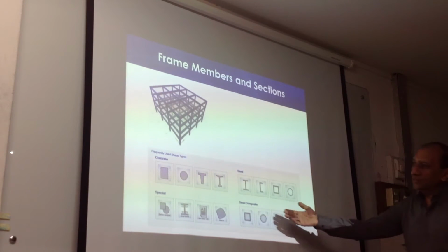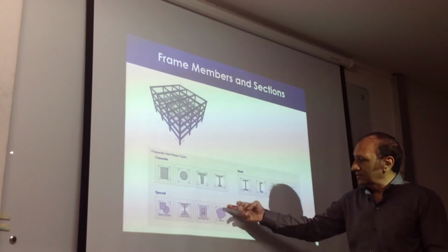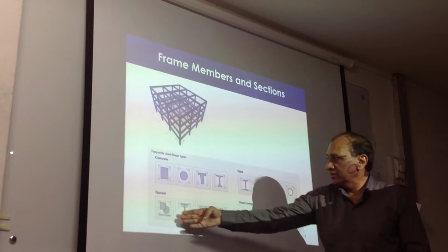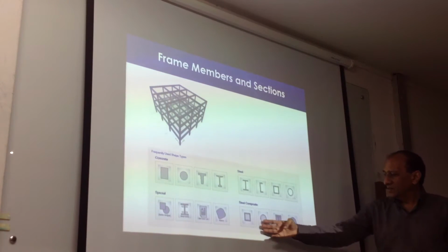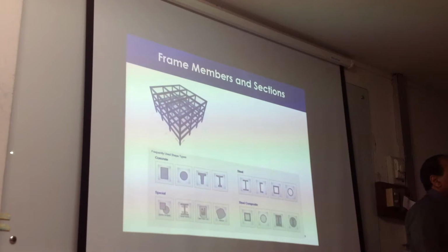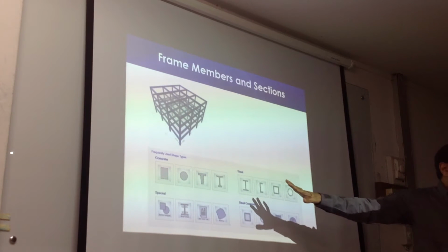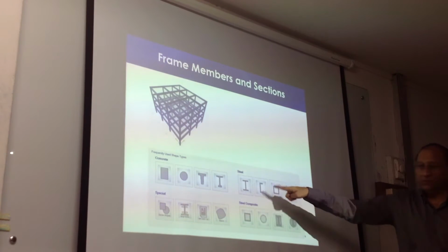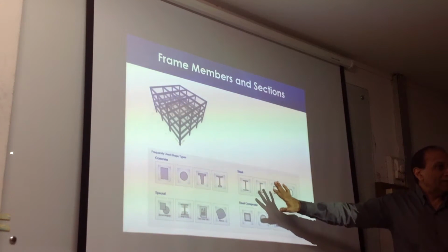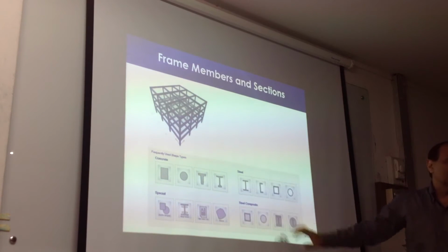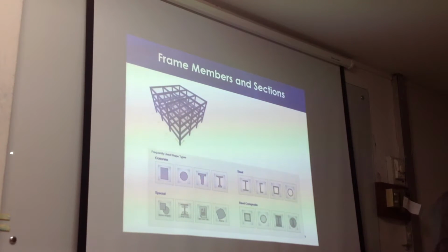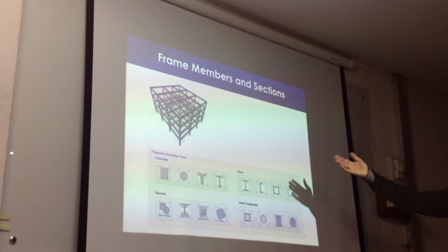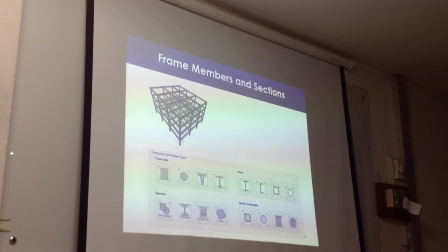And they may have any cross section here: rectangular, circular, this one, general section, built-up section, composite section, steel section. All those kinds of sections may be there. Steel inside concrete, concrete inside steel, concrete inside steel inside concrete, and all these combinations, right? Plus pre-stressing, post-tensioning as forces on top of that. And reinforcement anywhere. So we have a complex problem in the sense that we have so many types of cross sections, so many types of their combinations, and we have beams and columns to deal with.